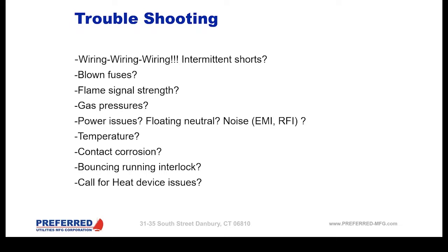What's the flame signal strength at pilot? What's the flame signal strength on main fuel valve? Is this where it was when it was actually originally commissioned? We could have an issue where it's simply just dirt or debris on the flame scanner that needs to be cleaned. Or we could have a flame scanner that has gotten weak over time. So that flame signal strength measurement is very crucial.